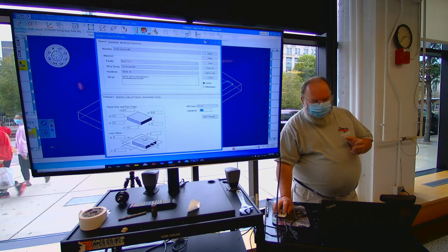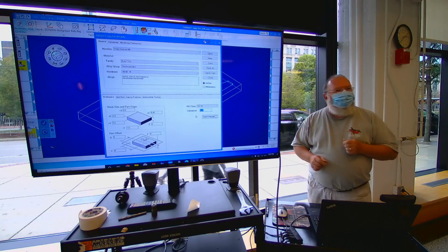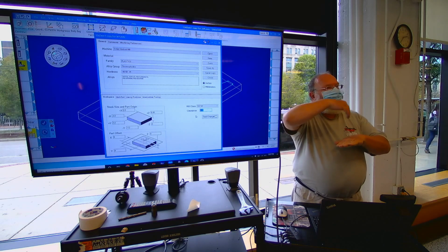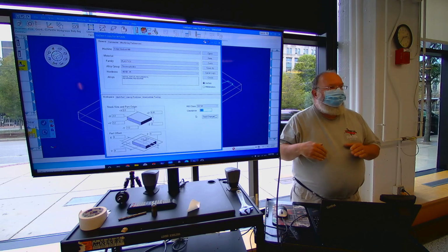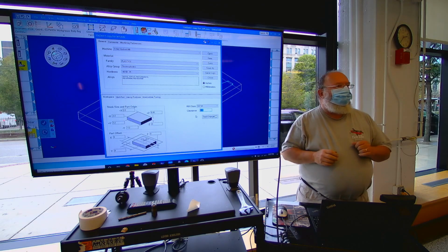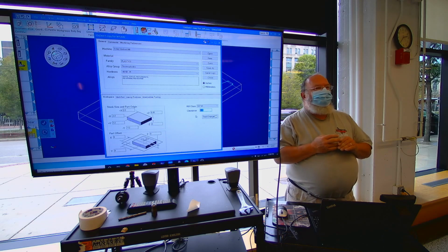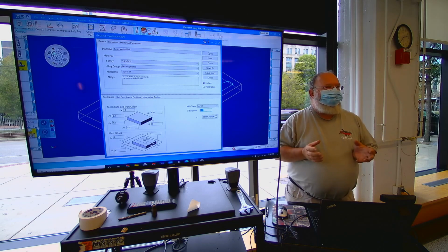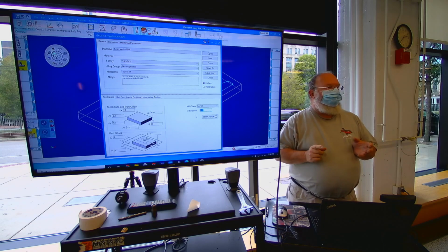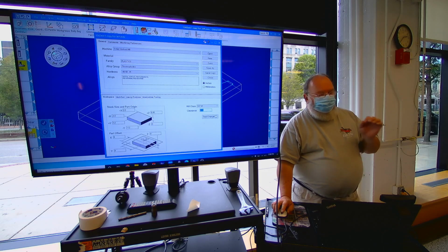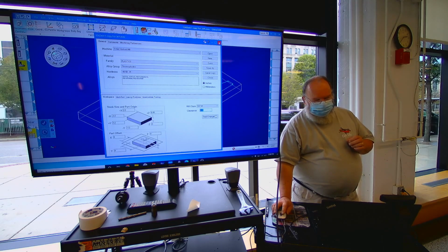And I come over here to probably the most important number in this window. This is the rapid traverse clearance level in Z. And when I say rapid traverse, if you look at the side of that machine, it says 1,000 IPM. That stands for 1,000 inches per minute. It travels in rapid. At that speed, by the time you realize there's something in the way, you're already looking at a pile of rubble. You cannot react as fast as this machine goes, okay? This is the first place we're going to see this. We're going to revisit it all the way down the line. So I'm going to close that.